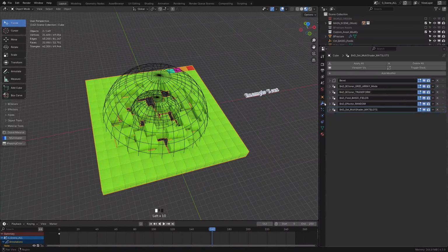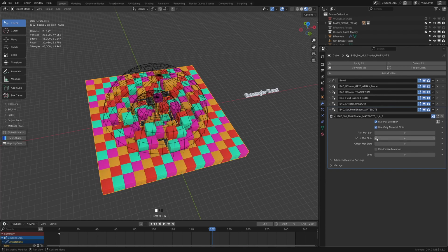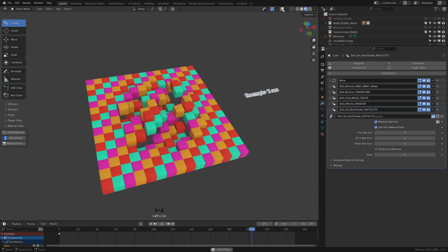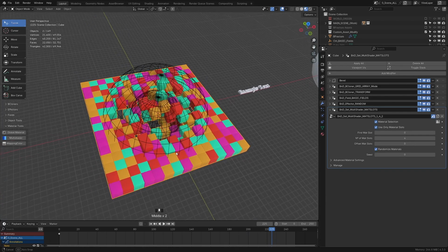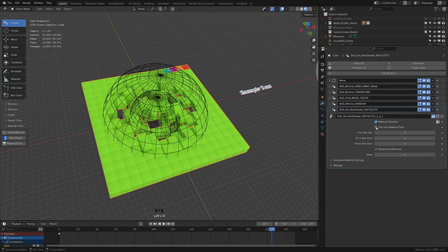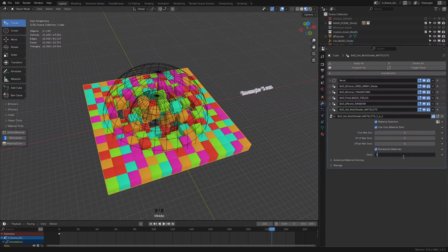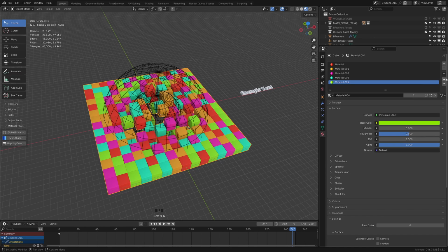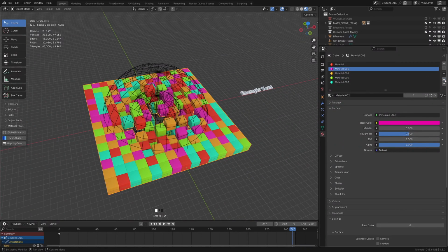But you can change it to activate use only material slots. So now the materials will be added in the same order. But once the last material is added, it repeats the same order of materials again to fill all instances. You can decide how many of the materials you want to use, and you can randomize them as well. You can change the seed if you need it. If you change the slot position of each material, the multishader changes accordingly.